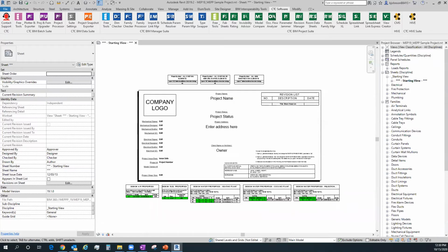All right, so anything over, say, 10,000 warnings in a model, that's when I would truly call all stop. Everybody pens down, do everything you possibly can to remove warnings from this file. So if you're not working on warnings, you shouldn't be in the file whatsoever. Go fix them. The most I've ever seen in one file within a company that I've worked for is over 14,000. It was less than 15,000, but I know it was over 14.